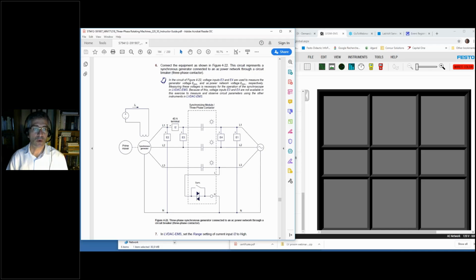By the way, if you wonder why we have voltmeters connected in parallel like this, it's that oftentimes we have tools inside our software that require their own voltage or current reading to perform their calculation. Okay, so whenever this is the case, these functions require their own voltage input, and this voltage input cannot be displayed in the meters.